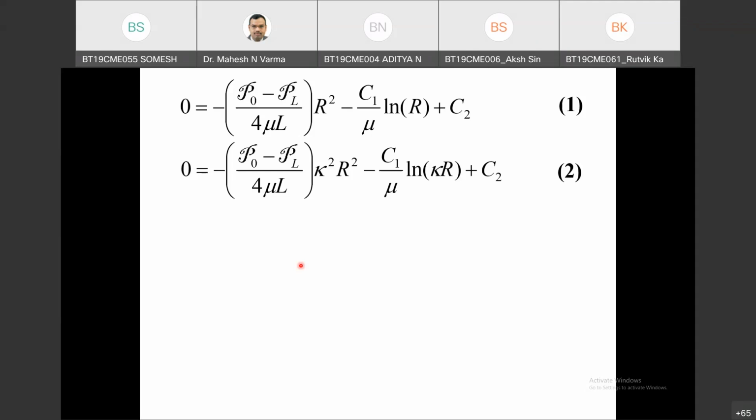The outer cylinder is bigger, so the first layer of water in contact with the bigger cylinder will have zero velocity, and the layer in contact with the inner cylinder, which is smaller, will also have zero velocity. No, this is the no slip boundary condition at the interface.